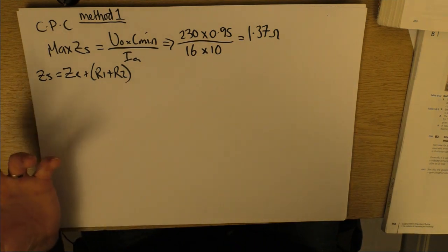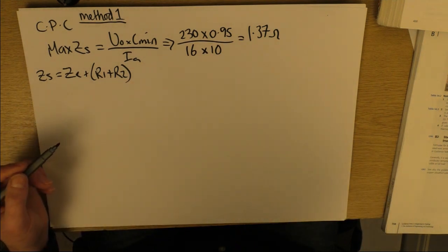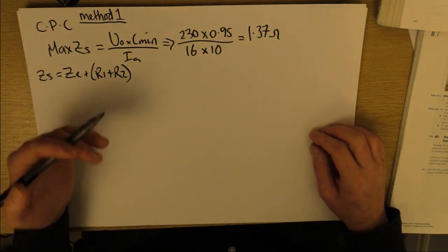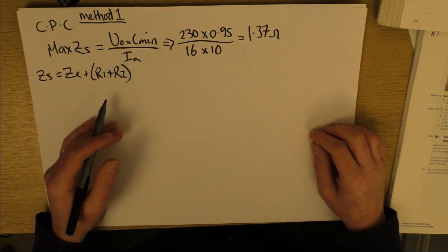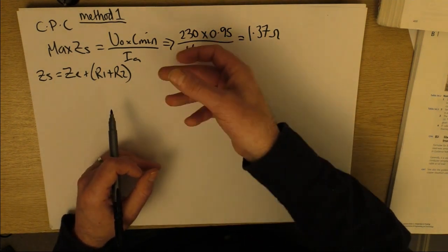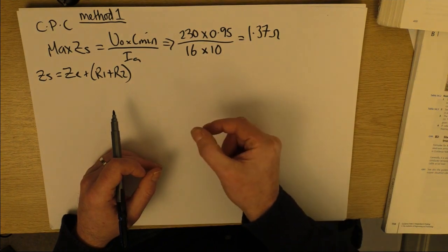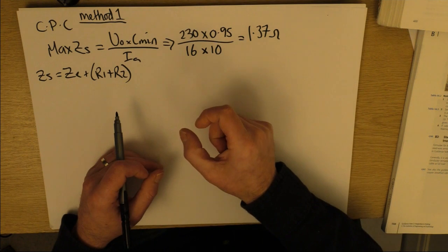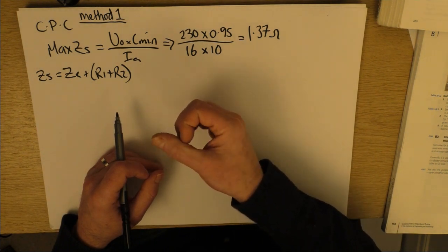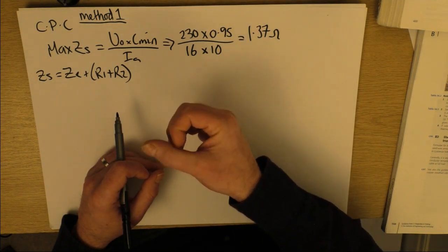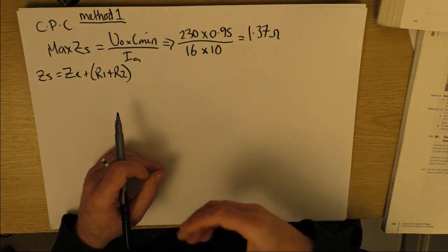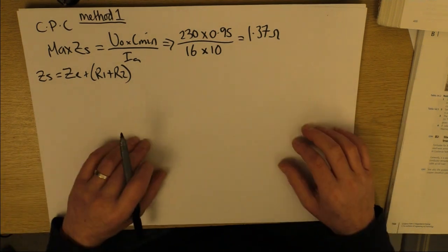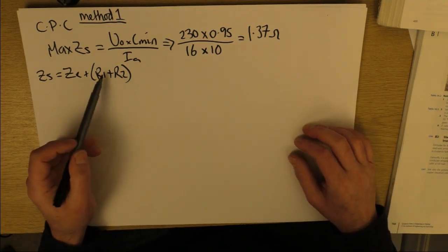I mean, you could calculate inductive reactance, it's 2 pi FL, but it's the L that's the problem in calculating. And especially with singles, it's not uniform, is it? It's not bunched in exactly the same way all the way through. In a cable, like a 3-core or a 5-core, they're together and predictable, so it's easier to calculate that. So for submains and big stuff, it might be worth doing, but for these kind of things,